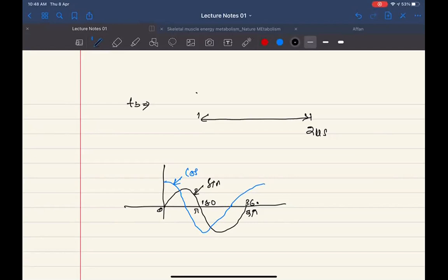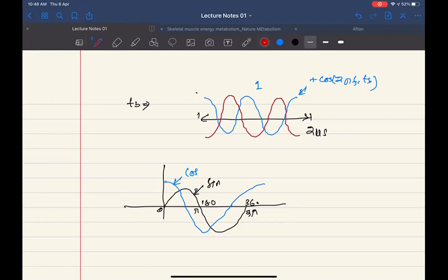And we use the cos signal. So the cos signal was starting from, for example, 1, 2. We were using 2 cycles for each bit transmission. If it was 1, we were using plus cos, which is this one, plus cos of 2 pi fc of tb. If you remember, we were using this one. And if it was 0, then we were using a signal like that, and this was minus cos 2 pi fc of tb.